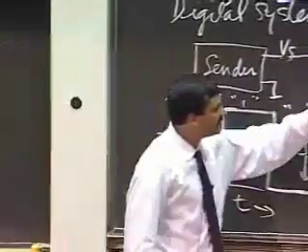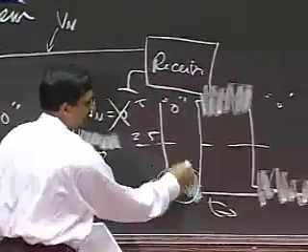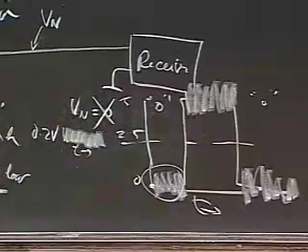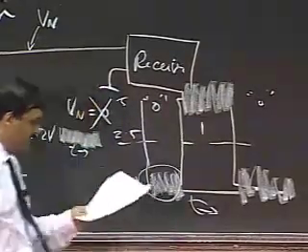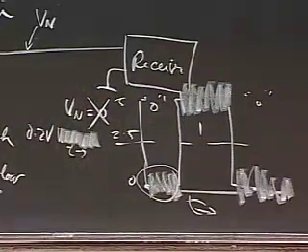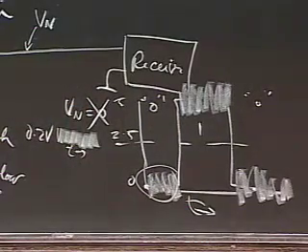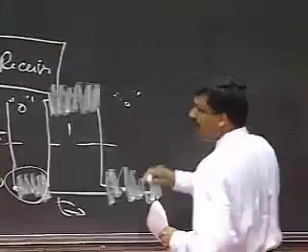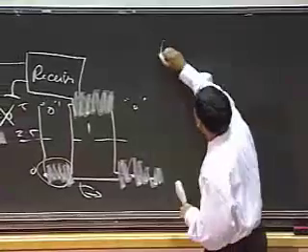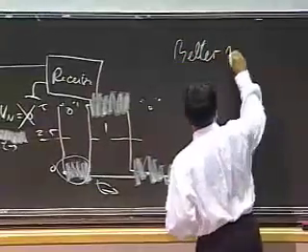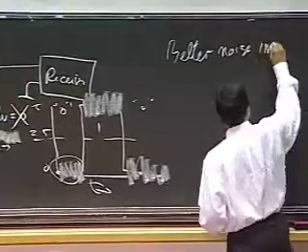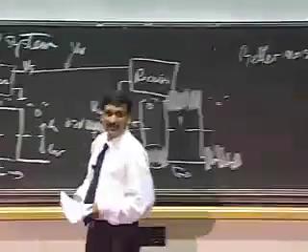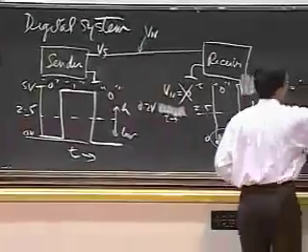But guess what? No problem. The receiver says, oh yeah, this is a 0 because the values are less than 2.5. This is a 1 and this is a 0. So 0, 1, 0. Here my receiver was able to receive the signal and correctly interpret it without any problems. Because I used this value discretization and because I had this agreement with the receiver, I had better noise immunity. Consequently, I had what is called a noise margin.